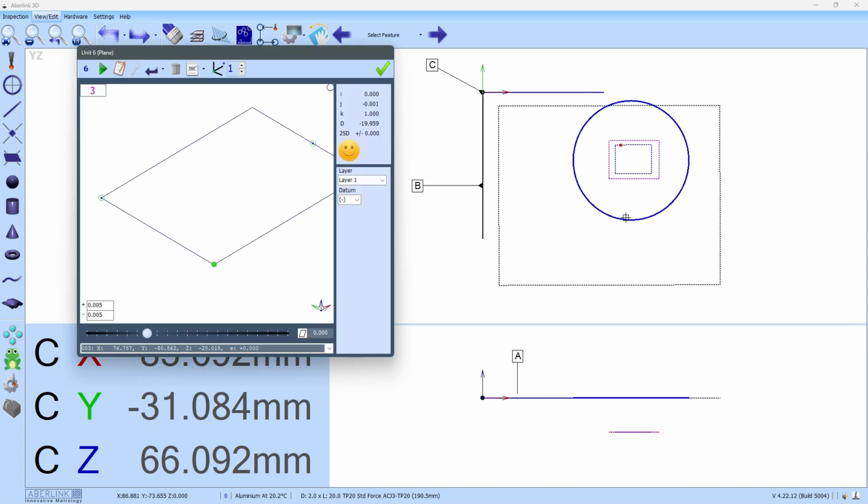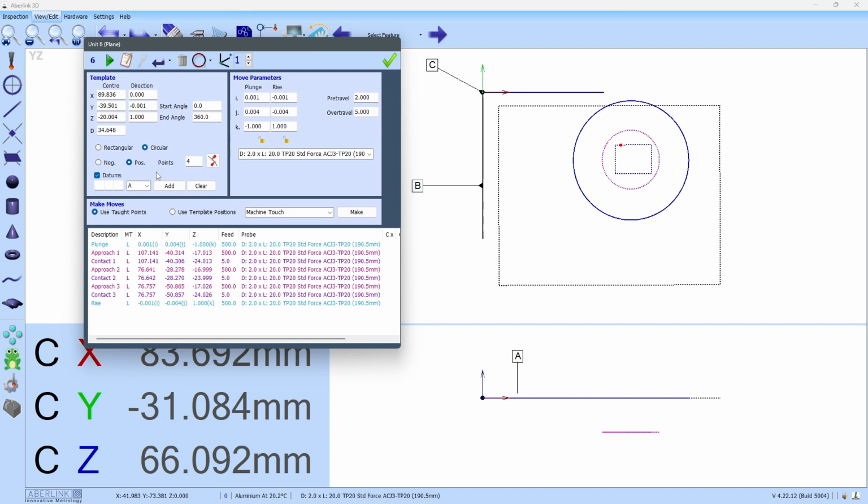of these planes, so let's start with the outer one, and I go to CNC and change it to circular, you'll see this position of where the circular center is and the diameter are all linked to the reference system. So the points and the template are all linked to this origin, this datum C, via the alignment of B and obviously the primary alignment of A.